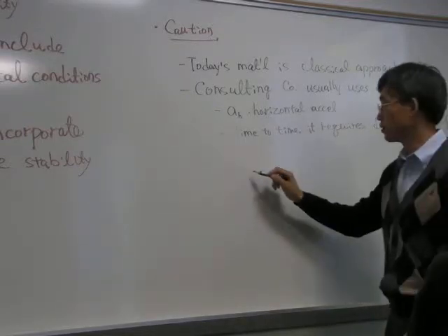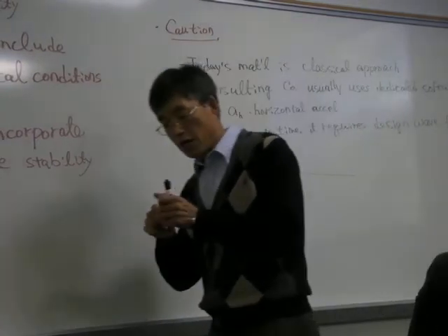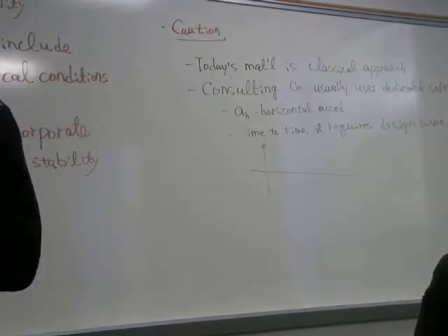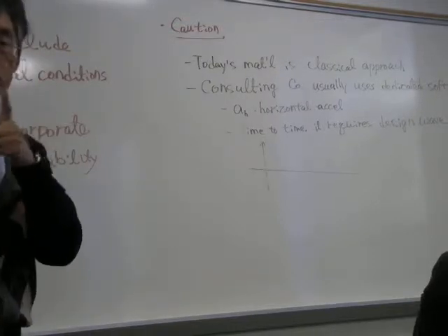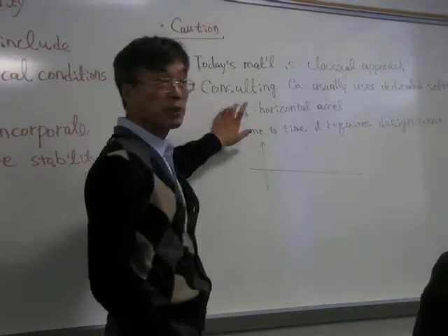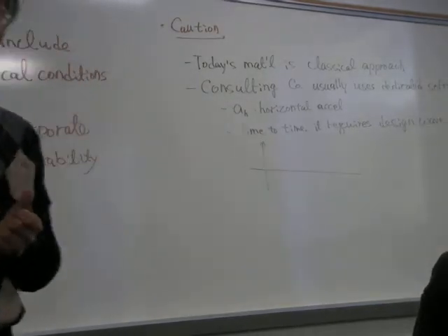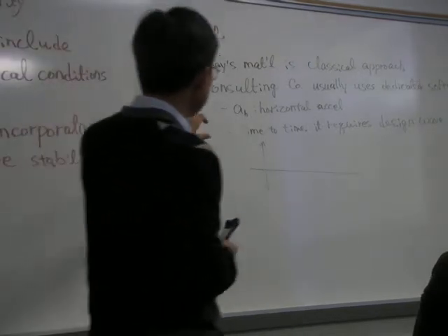Design waveform means, whenever we got to design something that may reflect our earthquake vibration, or maybe some machine vibration, usually there are two ways to incorporate those dynamic effects. First one is make everything very simple and just use the acceleration. Something like when we have earthquake record, we know how to convert it to the equivalent number of cycles with certain acceleration. That is a simplified technique.